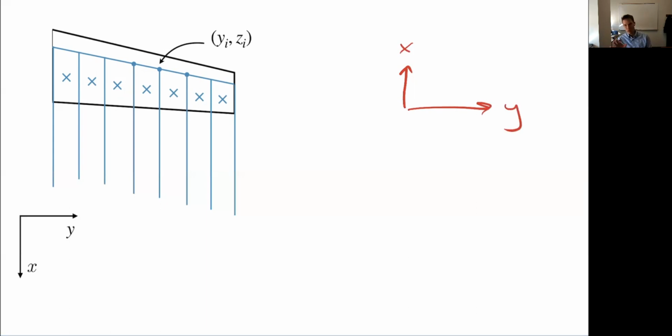There are also some subtleties in the X direction. For aerodynamicists, we usually think about the direction the wind is going, so this will be aligned with the wind, whereas for dynamicists, they usually align it with the body, which are not exactly the same, but we won't worry about that. The important thing for us is X downstream, Y out the right wing.